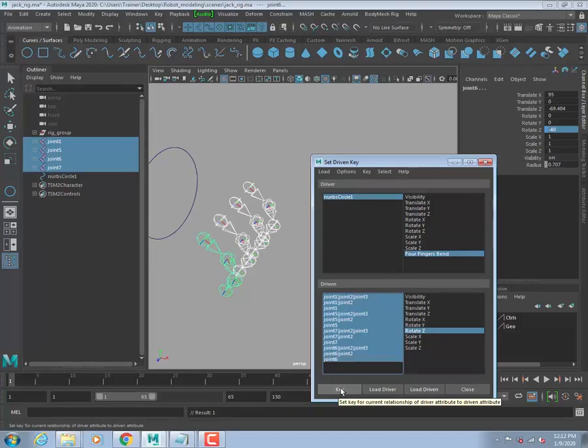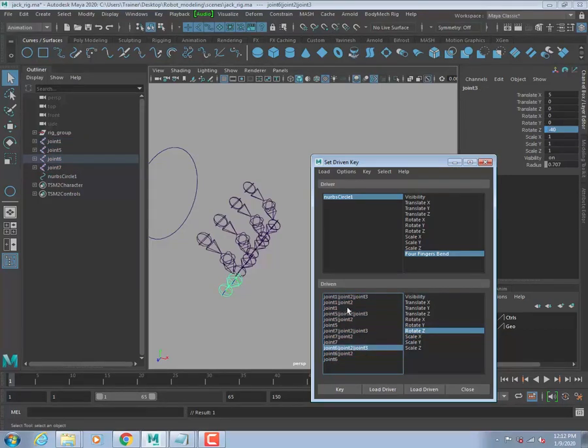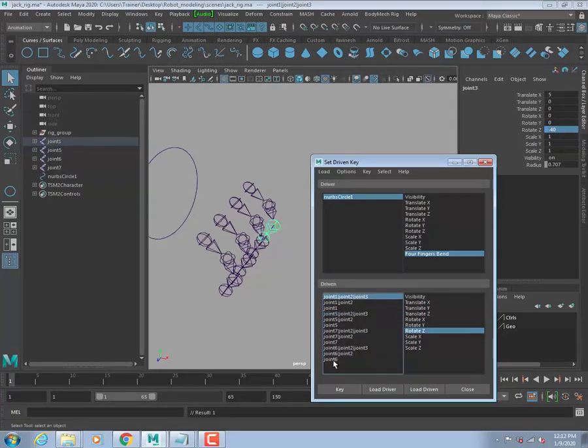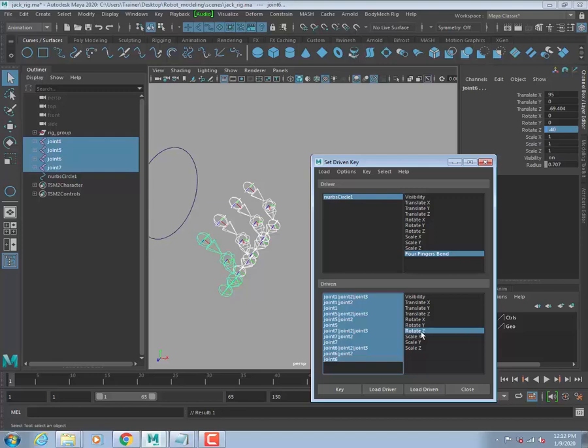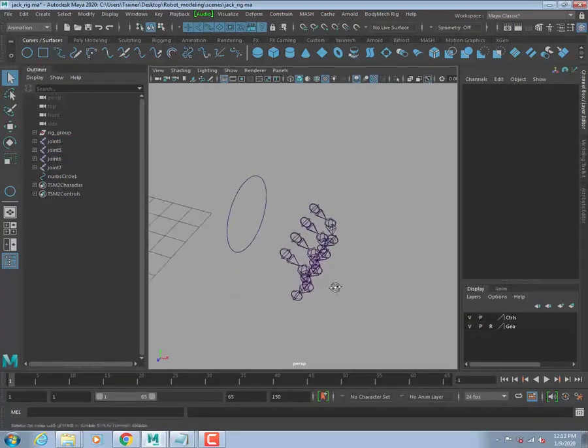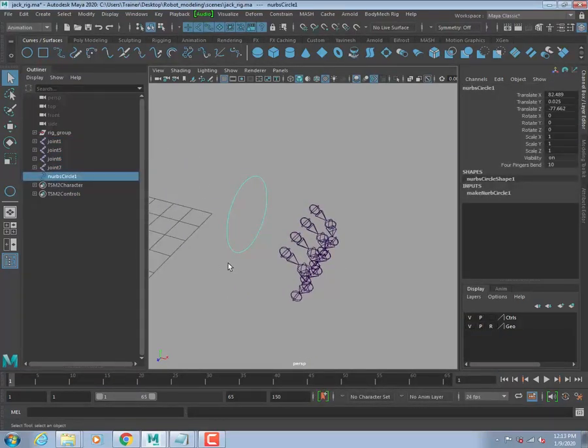Make sure of that. Sometimes the mistake people normally do is, even though they already changed the value, they forget to select the attribute name, maybe accidentally click somewhere else. If you don't select this, when you key it doesn't work. You will get an error message. So once we have done, we have 3 keys. First is 0.